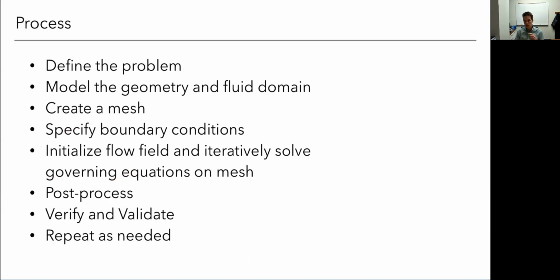But the other way we would do it, and this is a common technique, is where I might solve on a coarse mesh and then refine the mesh and resolve, and then refine the mesh and resolve. And sometimes that can help me get to a good solution, sometimes even faster, but at least if I'm having numerical difficulties, I can solve on the coarse mesh, and then that'll be a good solution for the finer mesh, and I can refine in some of these places where I may have had difficulties converging early.